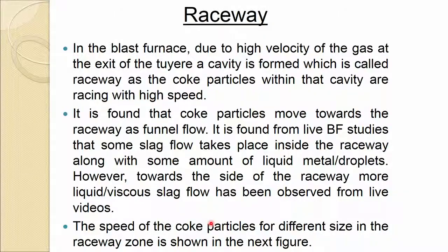And because this video which you saw is more related to the raceway, we would be talking about the raceway now. So, in the blast furnace, due to the high velocity of gas at the exit of the tube, a cavity is formed which is called the raceway, as the coke particles within that cavity are racing with high speed.